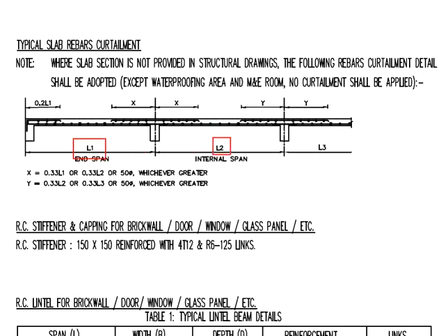Sometimes this span and this span are not identical. Therefore, it is wise for you to compute all 3 values before you decide. Whatever values that you obtain as the x, remember to round out to the interval of 25 mm. Next, if you are dealing with this part, same principles apply. Get 3 values, 1/3 of this span, another 1/3 for this span, and then 50 times the bar diameter. You choose the bigger value.